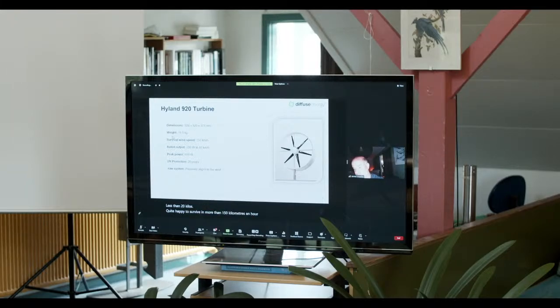We've measured that a couple of times out in the field. Rated output of 200 watts, peak of around 650, depending on some system parameters. And everything on the turbine is designed to last for 20 years. So the plastic has a 20-year UV protection, and obviously stainless steel for most of the components. There's some aluminium components, but they're a marine grade cast aluminium.